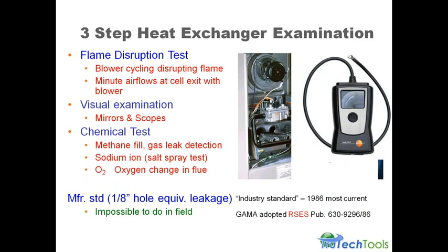And it's really, as an HVAC contractor, what you'd be watching, first of all, is you'd start the burner up, and you'd watch the flames. And we're seeing if the flames get affected when the blower kicks on. We're doing a visual examination with some scopes and meters, and we're doing a chemical test. I'm going to walk you through all 3 on these.